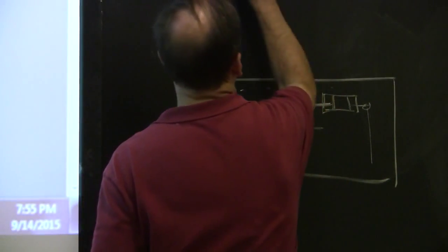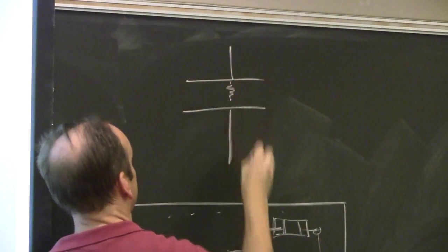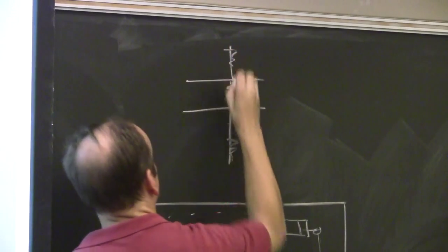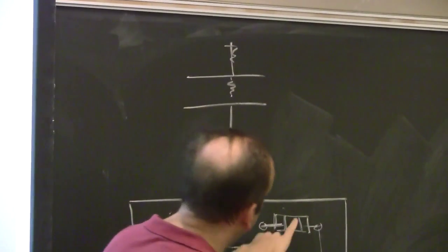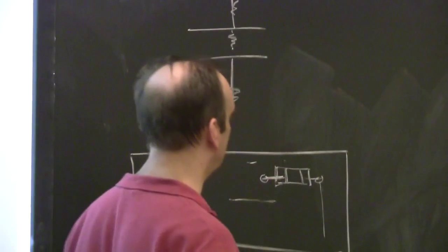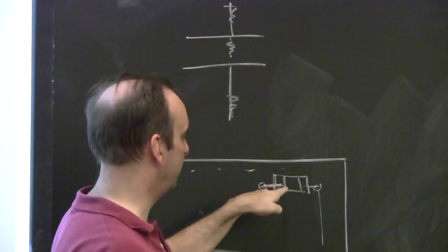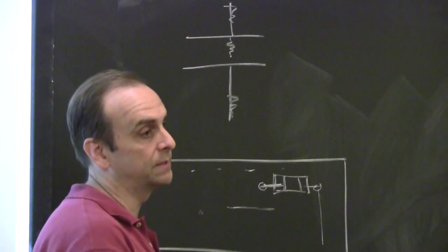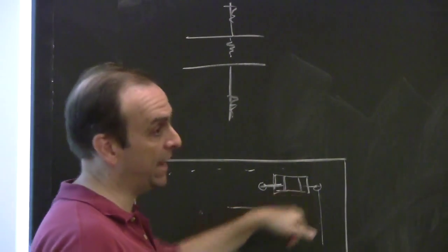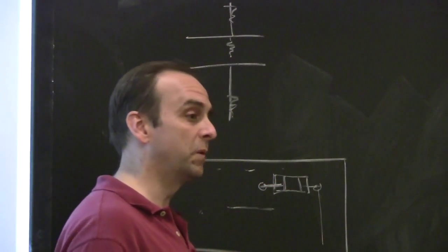Well, I don't want to do the whole thing from memory, but you think about it as a capacitor, but there's parasitics in here. There's a little bitty resistor in here. These guys have some resistance. You can pick up inductance here because you have to think about how the current is flowing between this element and what's supplying the power to it inside the board. So it's fairly complex. If you were to do a circuit simulation, it would be its own network of 4 or 5 different elements, of which the dominant one would be the capacitance, hopefully, because you're buying a capacitor, but you're getting additional things for free that you don't want.